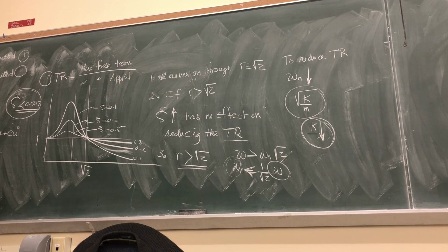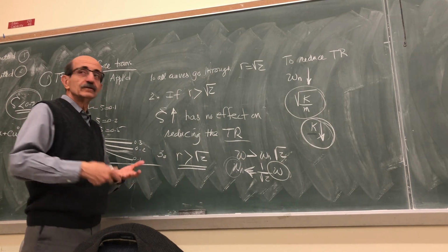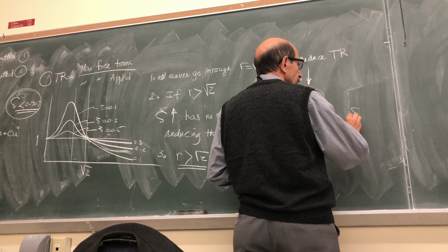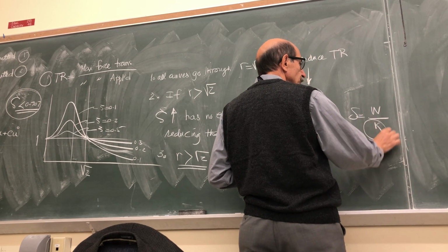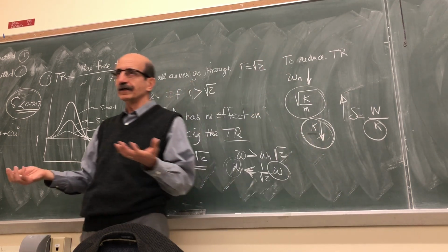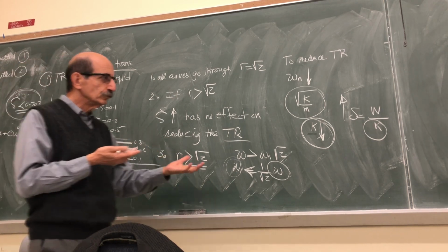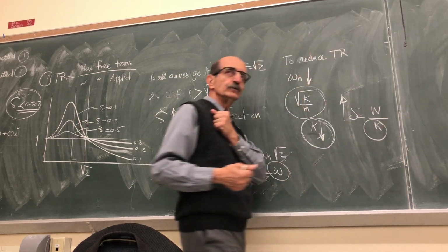But what happens is a give and take, right? What do you compensate instead of that? You get a large static displacement, right? Because static displacement is weight over K. So if you reduce this, your static displacement goes higher. So vibration isolation is a balancing act that you need to find out what is your optimum stiffness value.